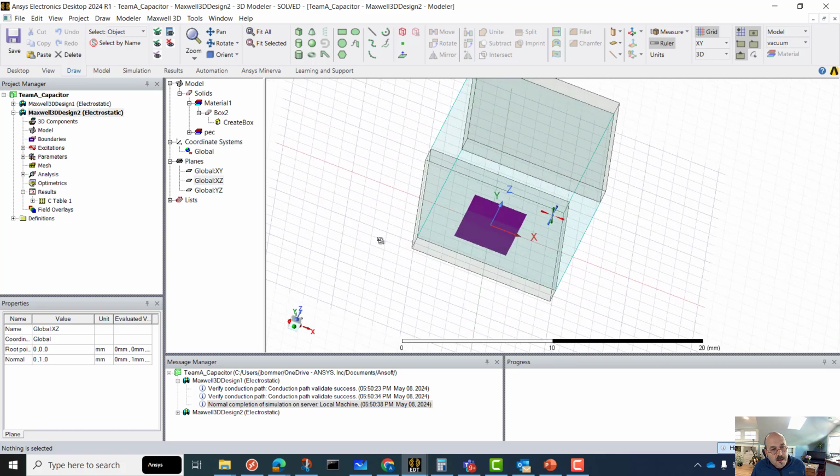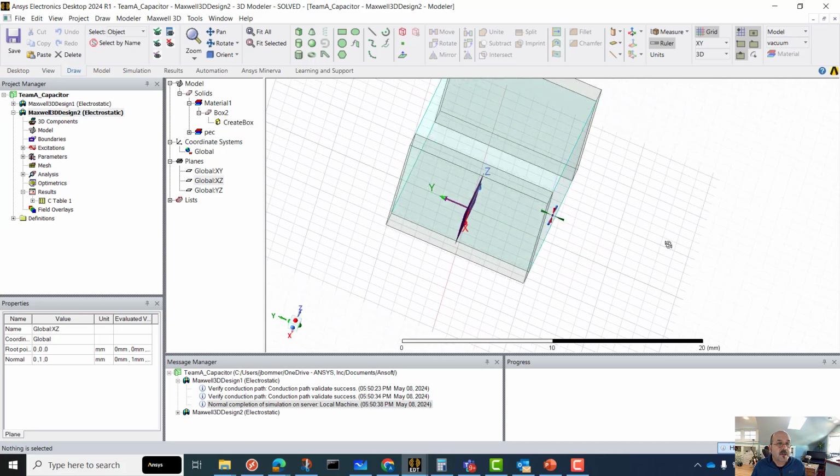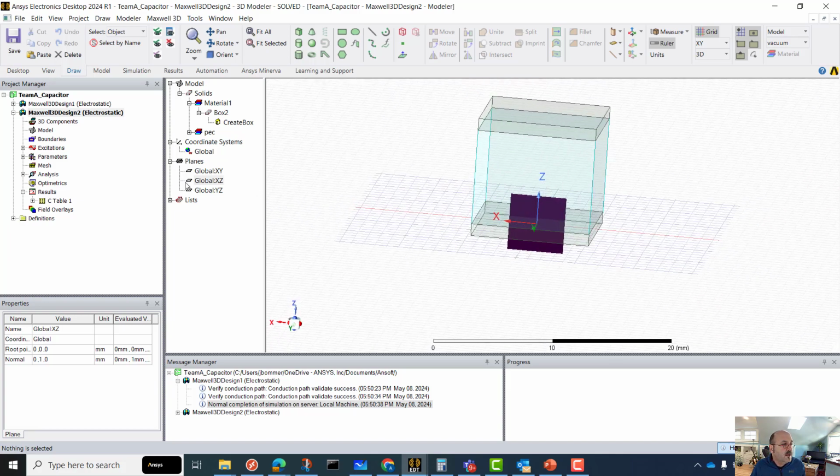What I want is a cross-section view, going right through this capacitor, and I'm basically going to say, plot the electric field vectors on top of this plane. That's all I'm looking to do. I don't know if we ever really talked about what they look like, so let's find out. I've got the plane selected. You have to have the plane selected.